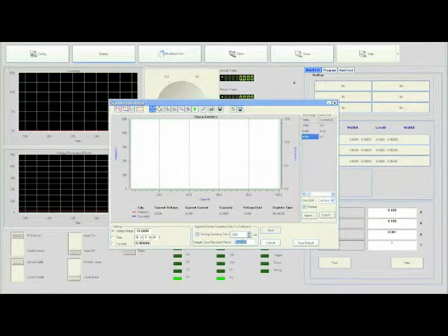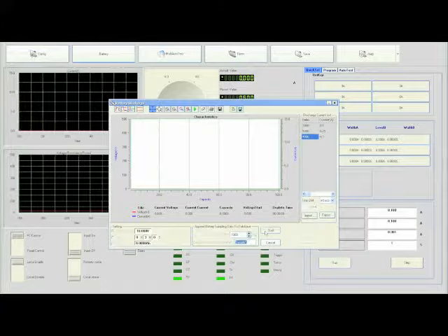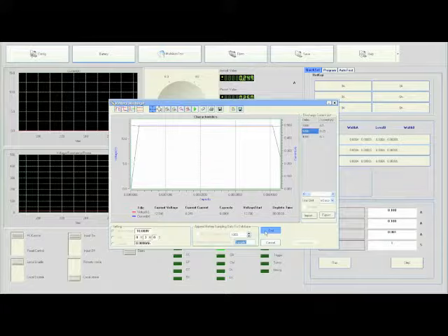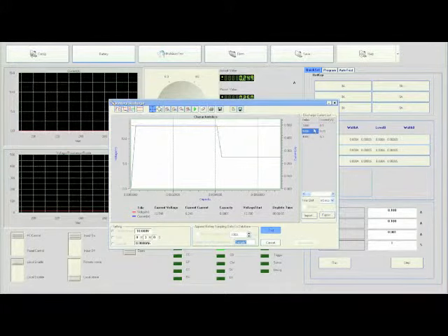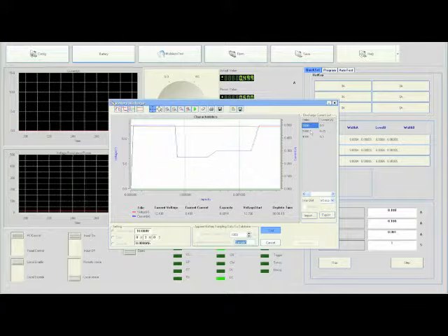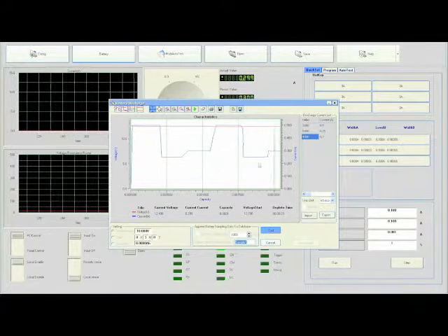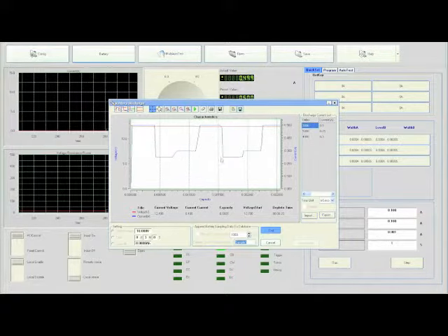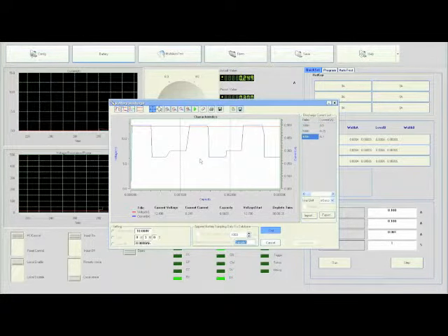Click the Start button to begin testing. The load will start testing the battery using values set in the discharge current list. You can see the test going through each step by the highlighted box shown here. The graphical display will plot the voltage and current throughout the test. Voltage is in red and current in blue. Notice that capacity as well as depletion time will be monitored constantly until the test ends.